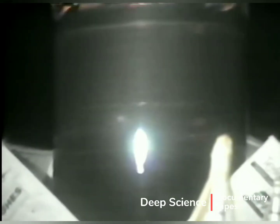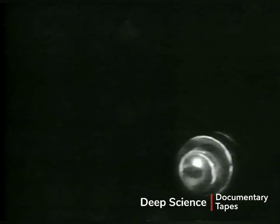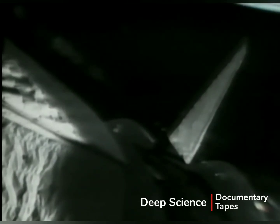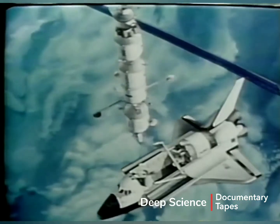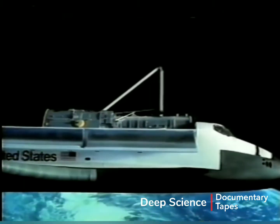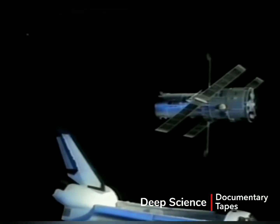Once satellites are launched and put into orbit, it is often necessary to change the orbit with an on-orbit burn. The common term used in describing on-orbit burns or engine firings is delta V. Delta V is the incremental change in spacecraft velocity measured in feet per second resulting from the burn. The amount of fuel used during a burn depends on the desired delta V change and the mass of the spacecraft. Because the amount of fuel carried is limited, fuel consumption is one of the primary considerations in spacecraft mission planning and is critical to orbit lifetime.